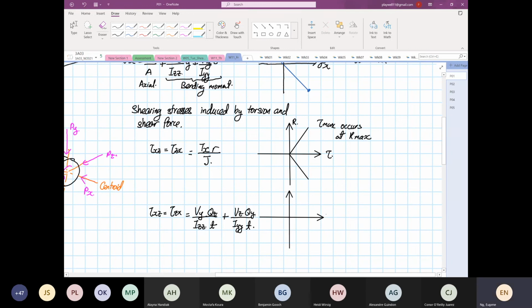So we have this, then this is our shear. We know the distribution now looks like this, and this can be y or radius. It can still be radius based. Our distribution is different now. It looks like this, and this is where our tau max is. So tau max occurs when radius is equal to 0.